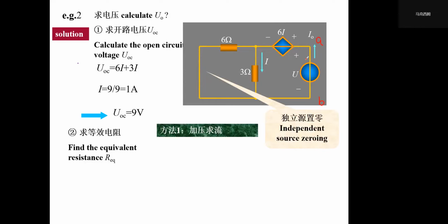So we have a voltage here, and this time the 3 ohm branch is in parallel connection with the 6 ohm branch, right? So since its current is I, the 6 ohm branch must have a half I, 0.5 I current, right? And since they share the same voltage, their currents must share the same direction.